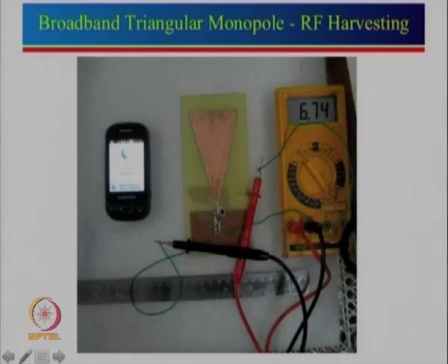I will give you that reason also, but let us just complete this part here. So in this case also one can actually get a fairly broad bandwidth depending upon the configuration. We chose this one here because of the pattern variation of this configuration over the desired bandwidth, which in fact we had designed for RF harvesting.